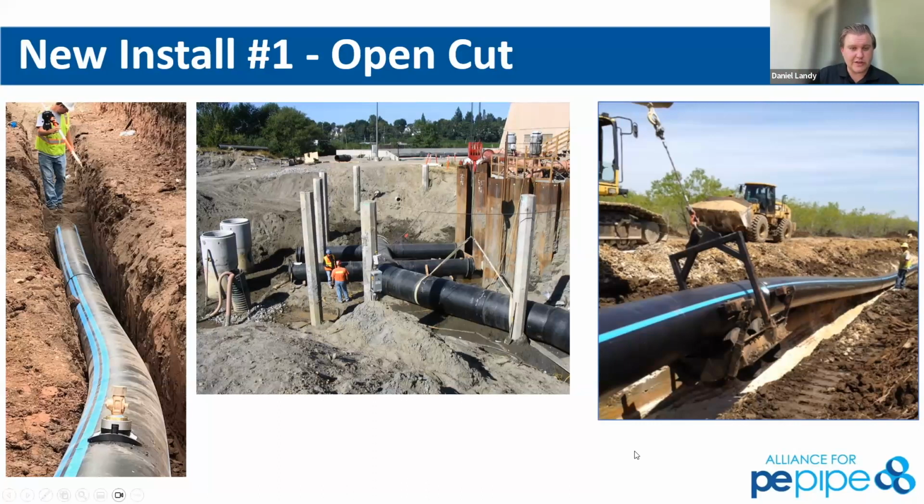One of the great things about installing HDPE, very similar to your ductile irons, your PVC, other pipe types you're used to, the M55, which is the manual for HDPE, actually has the same open cut installation requirements as the M28 and M23. Go ahead, Alan.